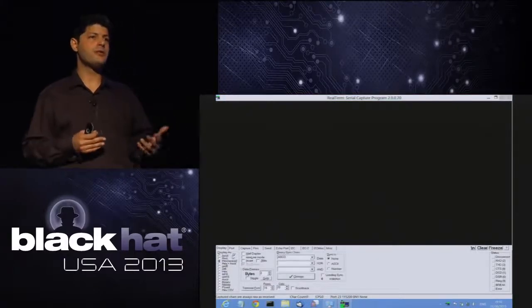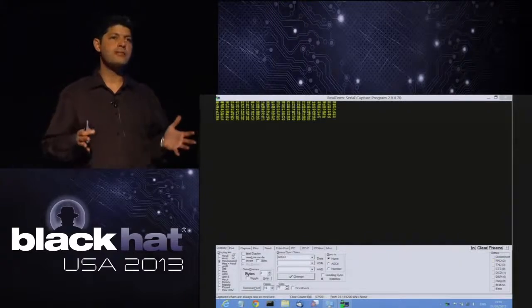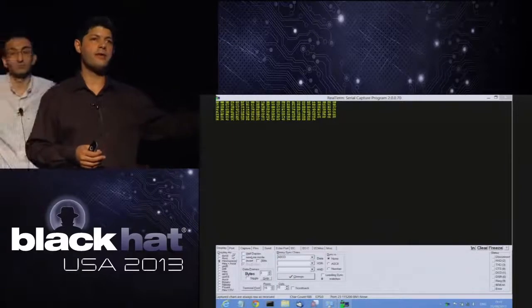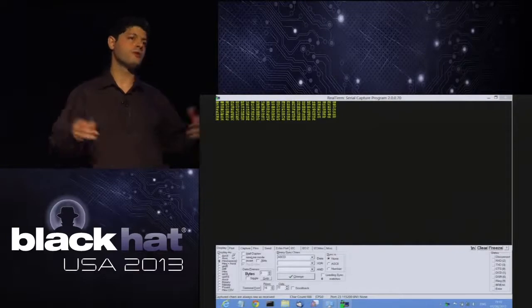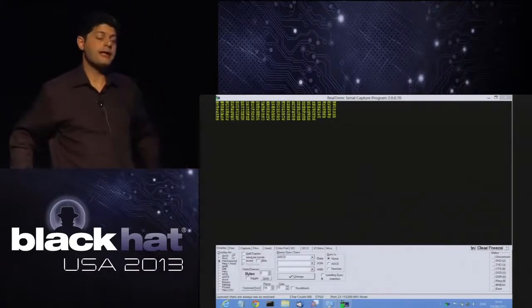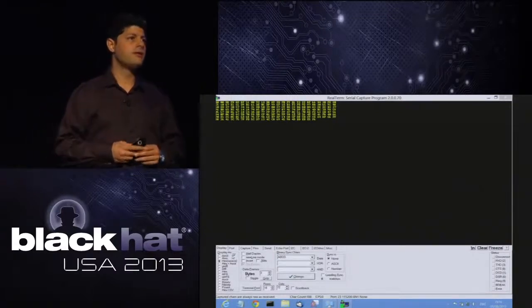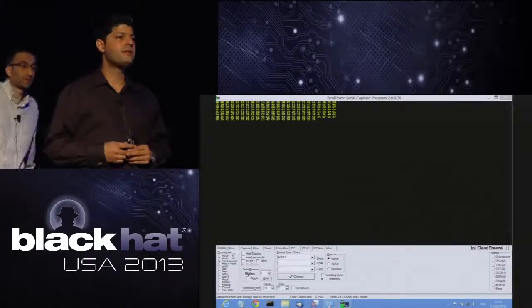So this can be worked around. It's not a protocol issue, but as a system, there can be workarounds. There can be watchdog mechanisms to prevent things like that. So if the siren doesn't hear anything from the motion sensor within a certain time, then it will go off because there's something wrong. So there can be things like that, but it is susceptible to jamming. You're welcome. Other questions? Yes, sir.